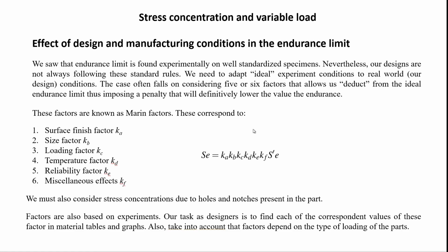What I have here is, let's call it, the theoretical endurance limit of the part. And that theoretical value is taken from the ultimate strength of the material, as we saw in the previous slide. Half of it, or 0.5 times the ultimate strength, is going to give you that value there.